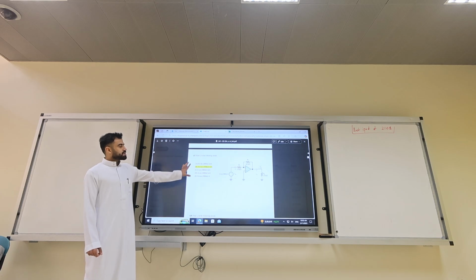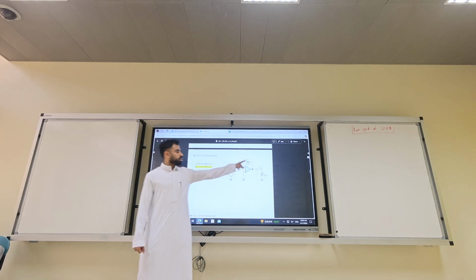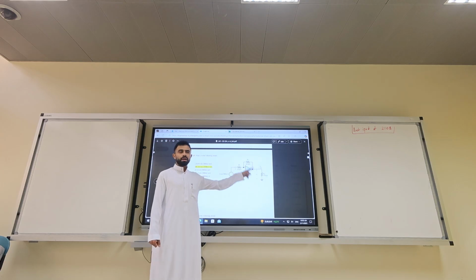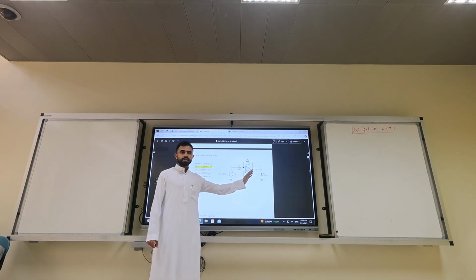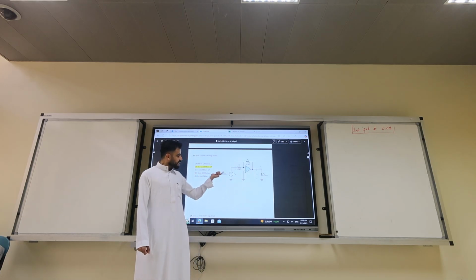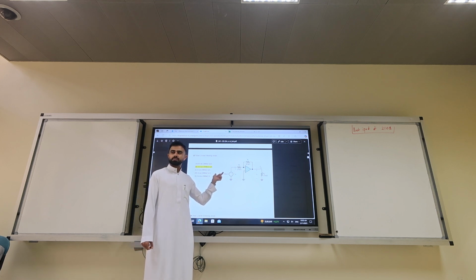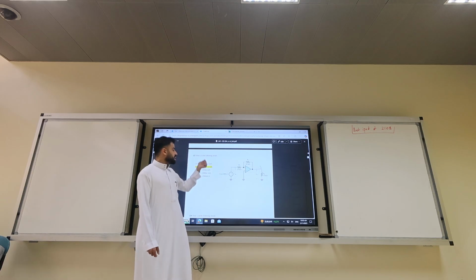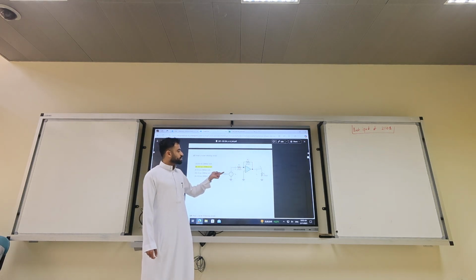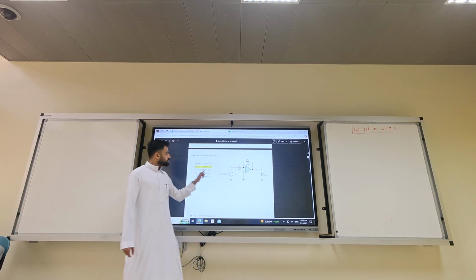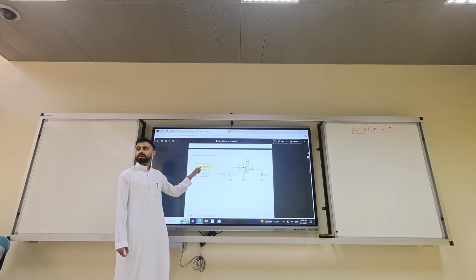Now, this is an easy problem, okay? We all now know this. What is this op-amp? Inverting input, negative feedback, classical inverting amplifier, right? Yes. Here, the only thing he wants you to know is he gave you the input as a sinusoid. And you can convert it to cosine, but he didn't convert the answers to cosine. So you just need to multiply it by the gain. So the only thing that changes is the amplitude. Get it? Okay.